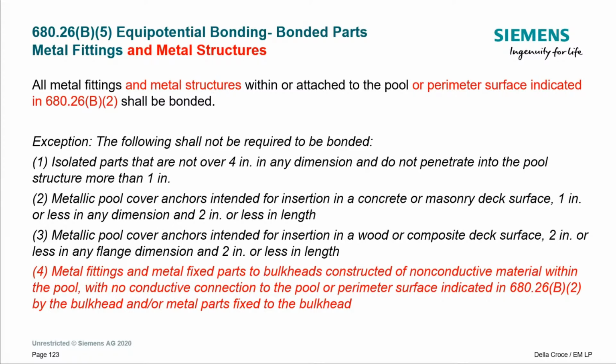it doesn't say "or." Right? 4 inches, or if it penetrates. Now, so it is "and." So if it's not over 4 inches in any dimension, and does not penetrate into the pool structure more than 1 inch, then that does not have to be bonded.